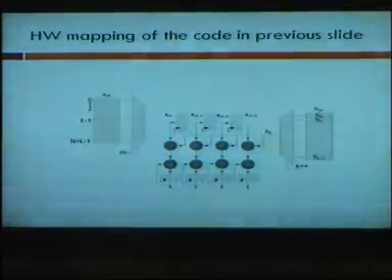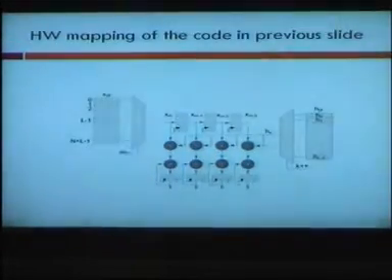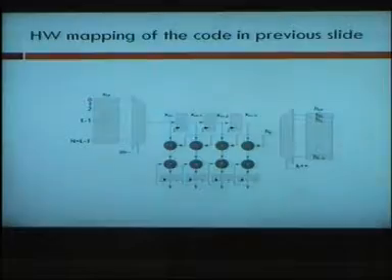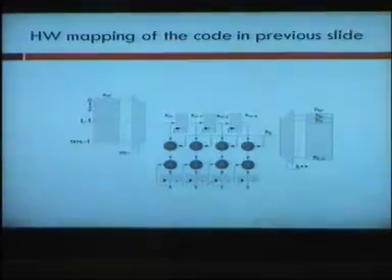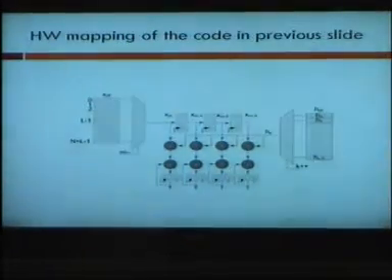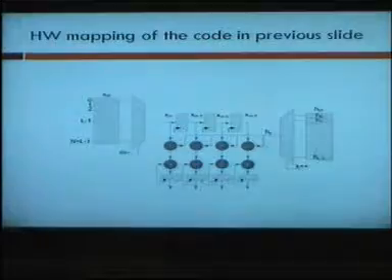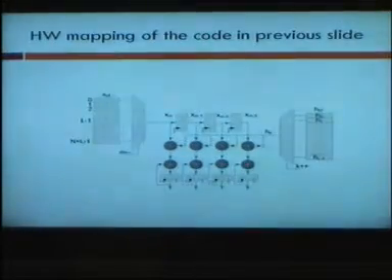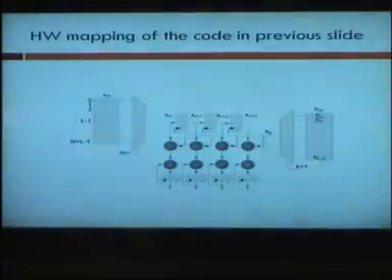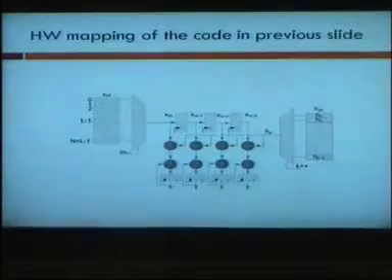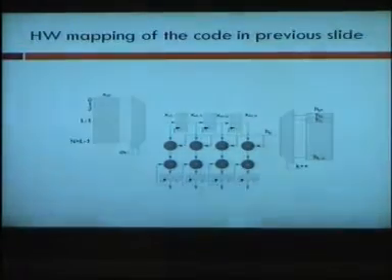This is a requisite. So you say, I have drawn this, then it is just a language like C, which most of you must be knowing. It's Verilog. Then you just sit down and write your code. And it's much easier to write Verilog than to write C. So that's another comfort, that there are no pointers, no pointers to functions. There are so many things which are not there in Verilog. So Verilog is a dumb, simple language.